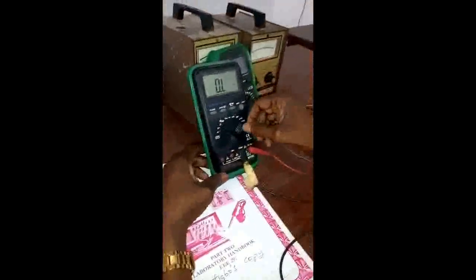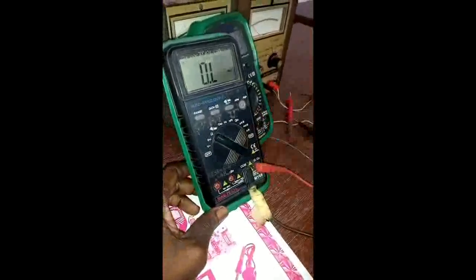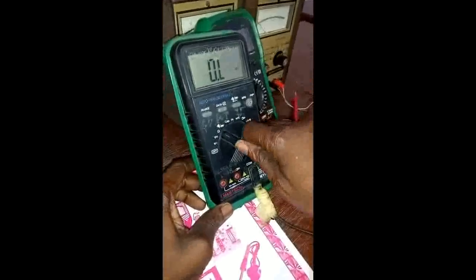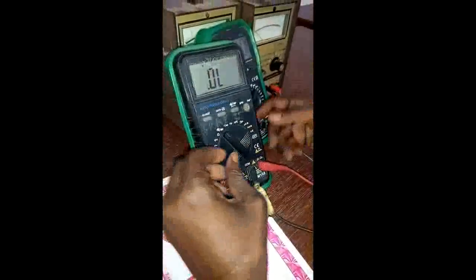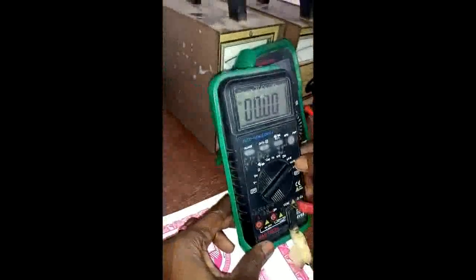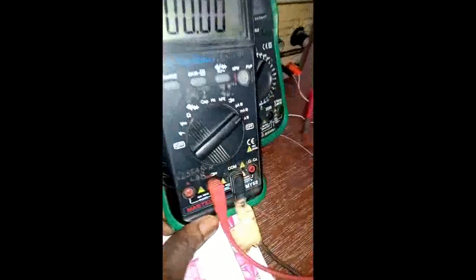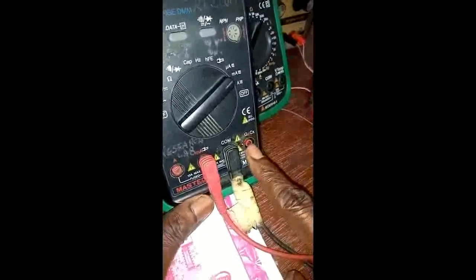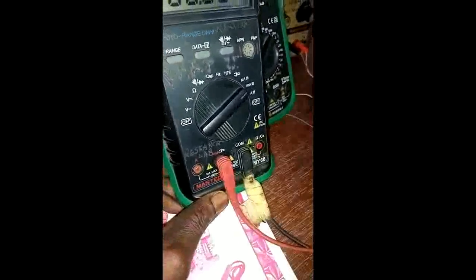If you want to measure diode, you want to know the effectiveness of any rectifier diode, which we are going to deal with extensively later in the course of this practical, you just select here, and so on and so forth. If it is for the current, like I told you, just come to current symbol here, milliamp. Then at that time, you have to change this one just like before. You remove it from this ohmic, voltage, and capacitance socket here, and then connect it here. That is exactly how to use it.